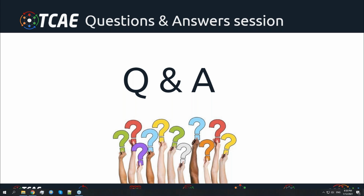Radek, can you see some good representative question you would like to answer? There are many good questions, but maybe we can postpone them for email communication because it's almost 5 o'clock. Maybe the last one: is parallel calculation possible for the inlet outlet interface with mixing plane? Basically, this method was set up with mixing plane and in parallel. So mixing plane and parallel calculation are implemented in our solvers. So yeah, it's possible.